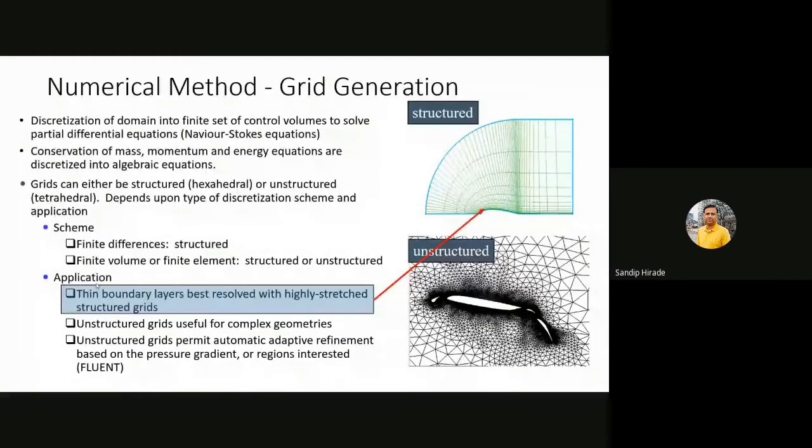And now for resolution of any boundary layer, we have to put a fine mesh near the boundary. Now you are seeing the aerofoil, where we try to find the flow behavior near the aerofoil. So we have to have a good mesh in and around the aerofoil. So this is how you mesh it. You have different types of elements you can go through: tet, hex, pyramid. There are a lot of different types of elements for the unstructured mesh. For the structured mesh, you have only the hexagonal element, and then you have two different types of meshes, again 2D and 3D. So you define whether it is a 2D problem or a 3D problem, and based on that we have to discretize the domain.